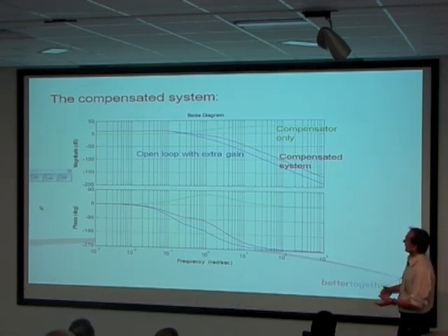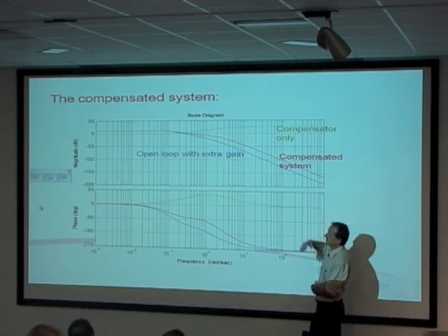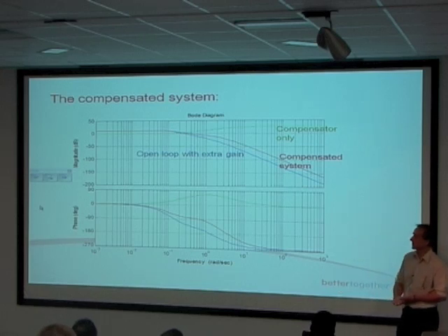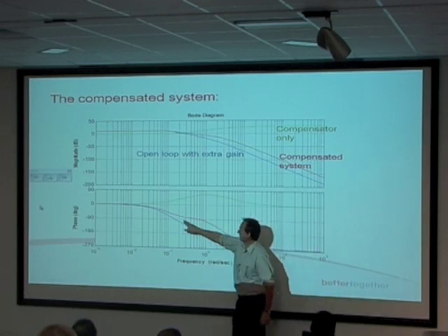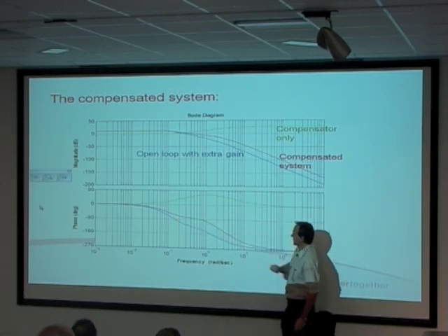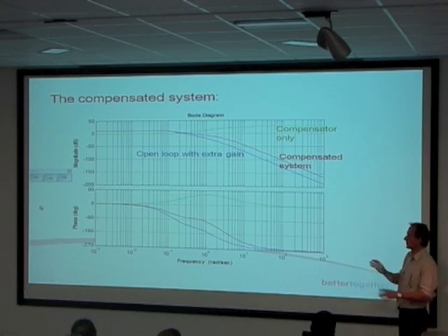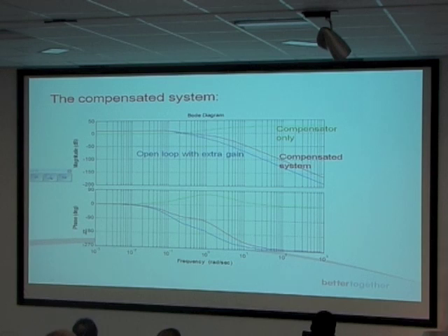Okay, you can see fairly easily what's happened is the blue one, the system standalone, the gain's been lifted a bit at high frequencies, but more interestingly, what we've done with the phase plot here is you can see we've put that big bump in it, and we've put that in there just about where we're concerned about gain and phase margins. Yeah, you okay with that? Just adding this extra bit in.